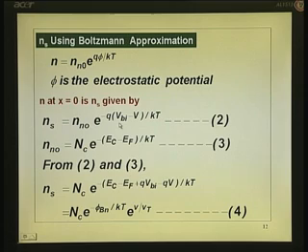So, now what is Nn0? Thermal equilibrium carrier concentration. That is related to Ec minus Ef and the density of states at the conduction band. This again is a standard formula in semiconductors. Nn0, the thermal equilibrium value, equals Nc e to the power of minus (Ec minus Ef) by kT.